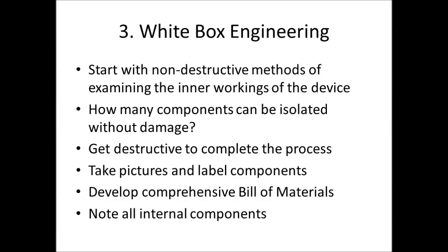So you might have to break some things out of their holders, break some chips to access other parts to get deeper and deeper within it. And that's okay. You want to be patient before that. Make sure that there are no other options at that point. So take pictures, label everything. And this is all going to help you build up a bill of materials that you put in the appendix of this report. So note all the external parts, and then note all the chips, all the components on the inside as well.